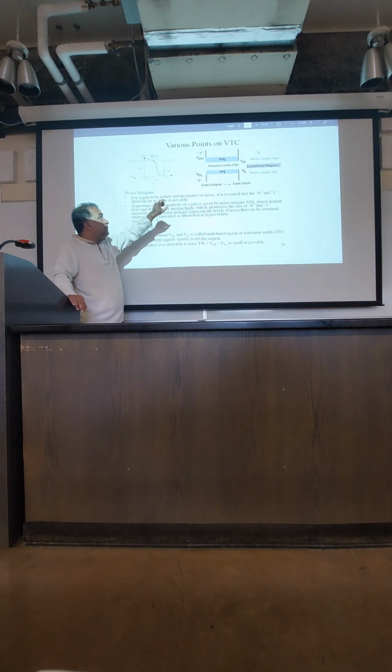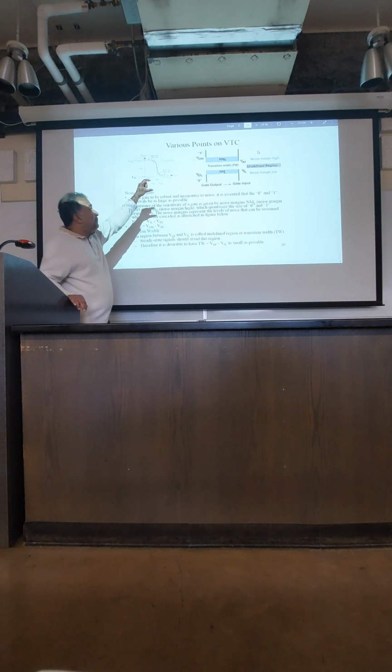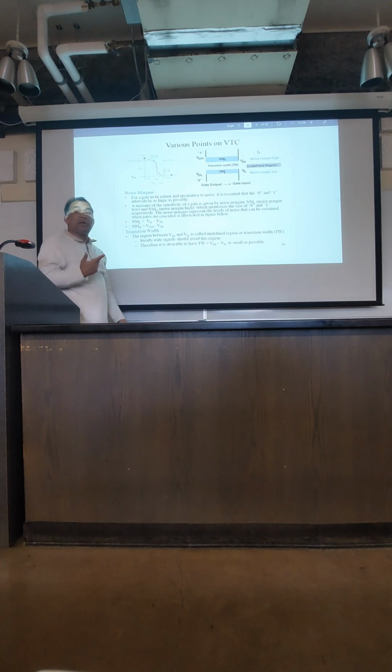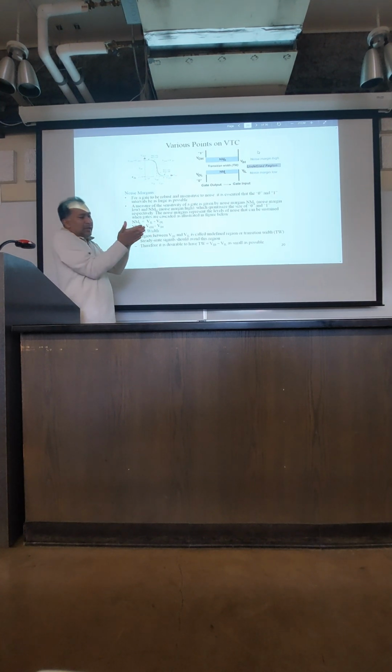So the noise can push the voltage inadvertently from low side to high side and high side to low side if the gap between the valid low range and valid high range is too narrow. So from a noise robustness point of view, having too narrow or short a transition width makes the circuit vulnerable, because then it can flip with unintentional noise from one side to the other.